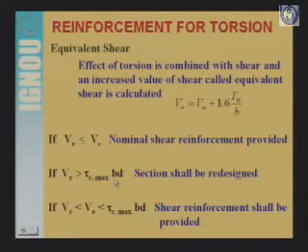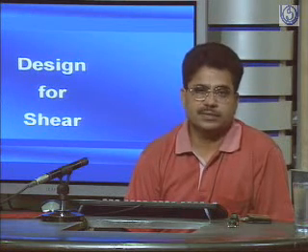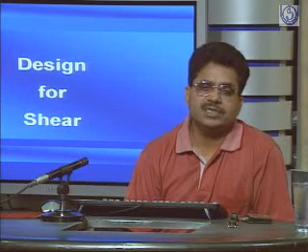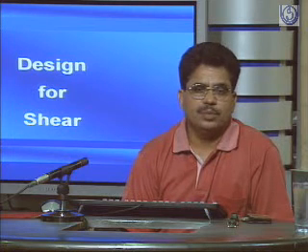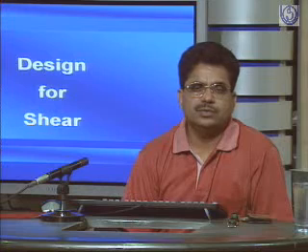Then similar to the previous case, we will go for redesigning of the section, because the equivalent shear is crossing the maximum shear-carrying capacity of the section. For such a case, the only remedy is to redesign the section and bring Ve down at least to equal Vc.